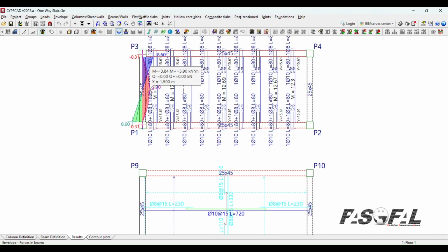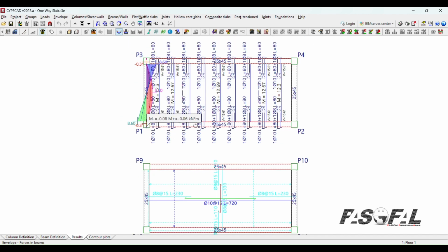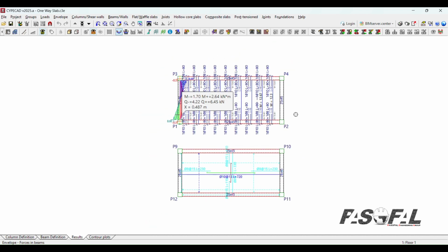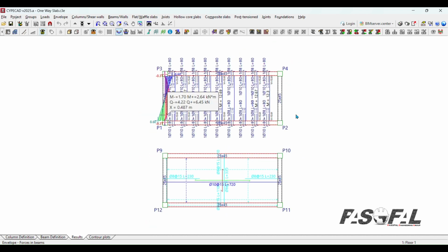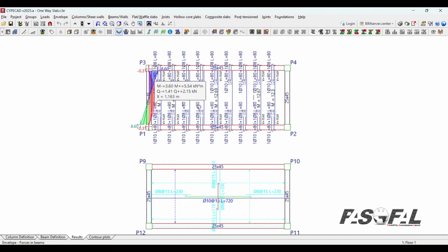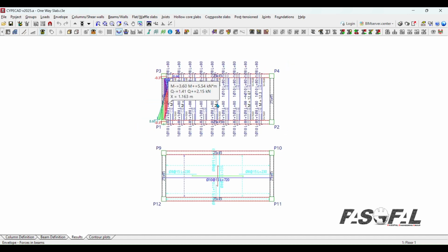As I told you, it can be due to the weight of the beam itself. So this is the way to model the one-way slab. Once you want to model the one-way slab, you can ignore the slab results here. We can just take advantage of joist or ribbed slab systems to model the one-way slab and check the beam results.